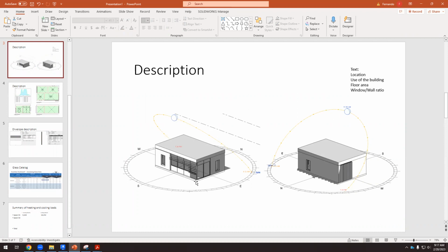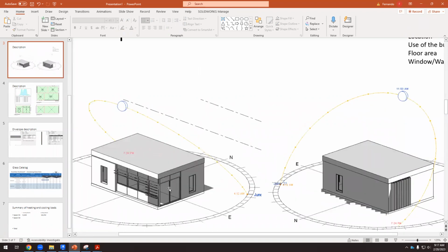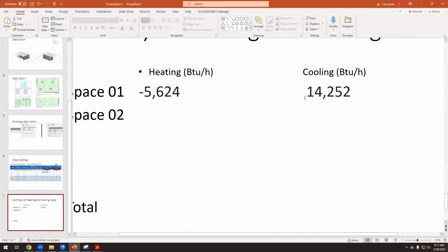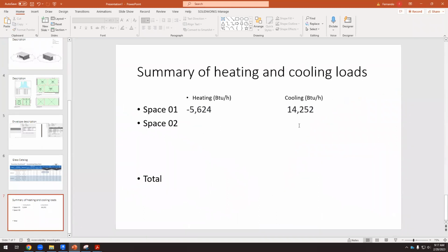But I want you to do something else. Okay, so I want you to keep the aesthetics of the building, just replacing probably some of the transparent panels by some of opaque panels, and try to add shading devices to that in order to reduce the cooling load of those spaces.